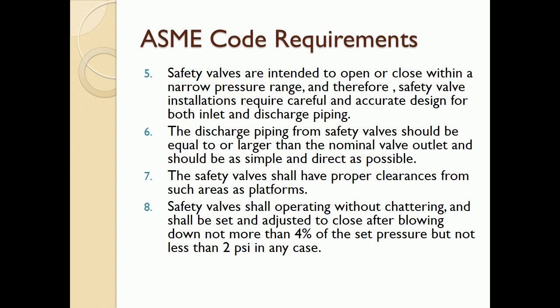5. Safety valves are intended to open or close within a narrow pressure range, and therefore, safety valve installations require careful and accurate design for both inlet and discharge piping. 6. The discharge piping from safety valves should be equal to or larger than the nominal valve outlet, and should be as simple and direct as possible.